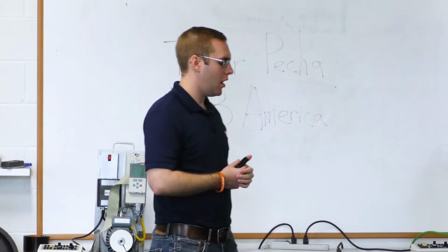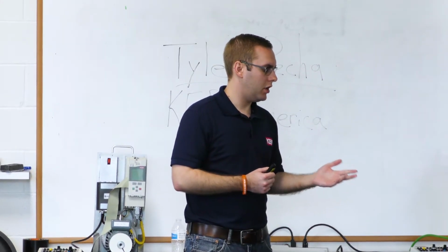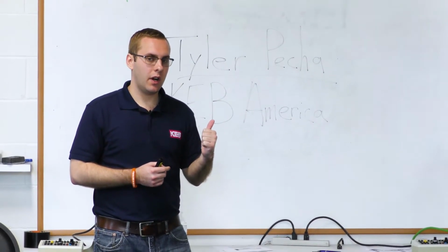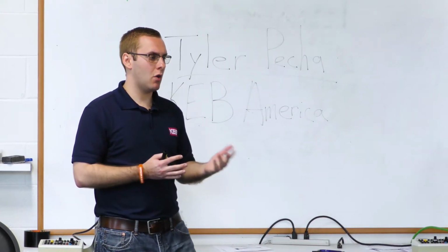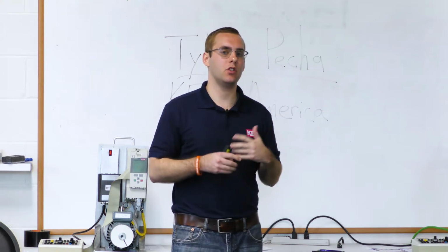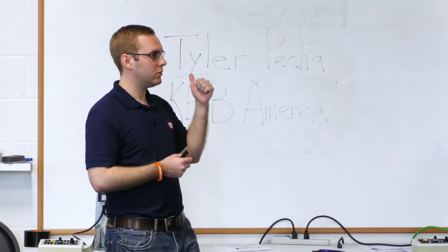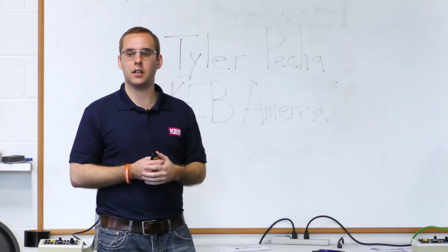Another note on this: when you do a motor tune, you might actually get this right away, and you might think, well, I'm doing a motor tune, what difference does it make for the encoder? The channels need to be there all the time. So the drive, when you go to do the tune, is actually looking at that. I have seen too on a number of occasions that when you go to do the motor tune, you get this error. Again, it likely indicates that you're missing a channel pair.